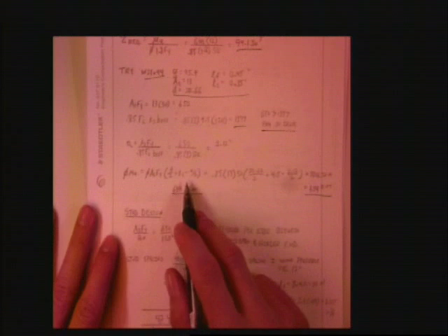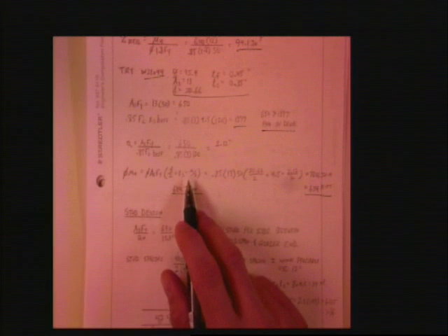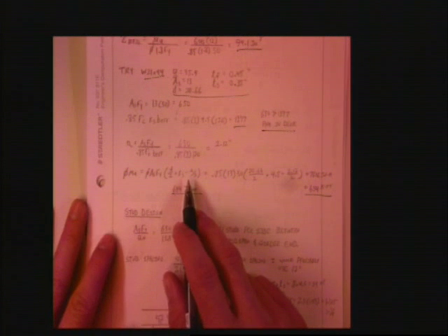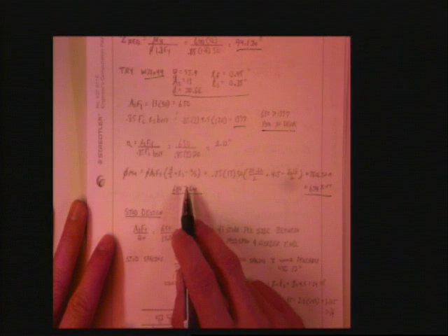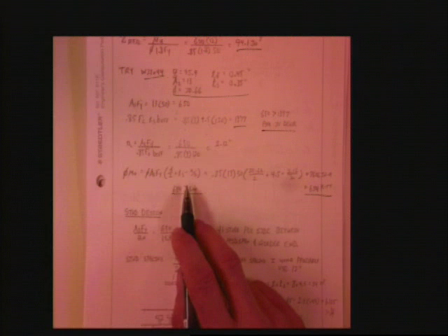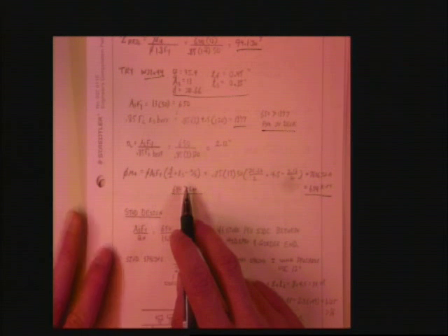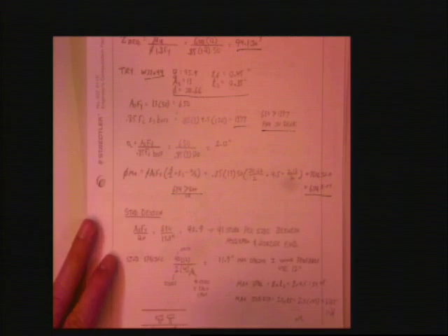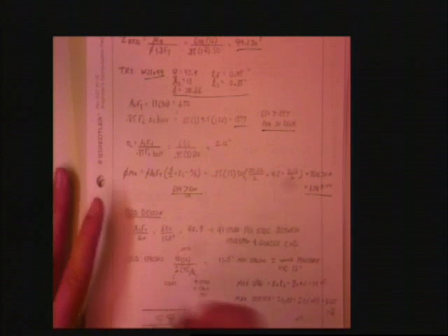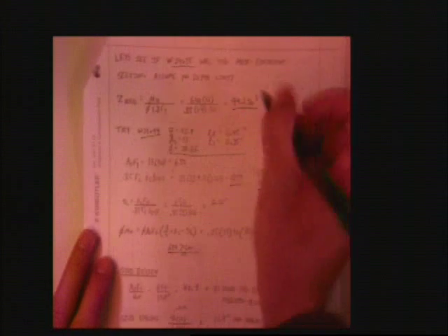And composite girders are a little tough to decide. How much does my deck give us? But for typical sizes in buildings, and actually this works for bridges as well, up to about 8 inches thick a deck, this technique works really nicely. Start to get things that are much larger than that, it starts to break down. But it works real nice, and that's what we want. We want simple things to get us in the ballpark. We did that real quick.